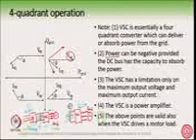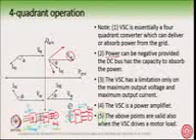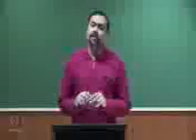Basically we also see point number 4, that the VSC is a power amplifier. It amplifies the voltage and current, so whatever reference you give, it reproduces it, but with a larger magnitude at the power level. Basically the VSC is a controllable voltage source. So it's a power amplifier. This is an important point. But it has a limitation. The VSC has a limitation on the maximum output voltage and maximum output current, which means that the voltage source converter, from its design or from the way it is built, has this maximum output current.